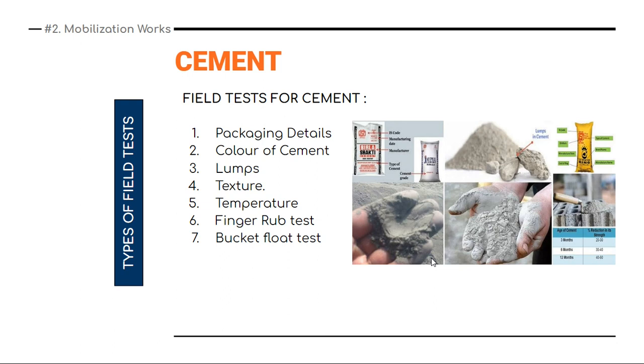It means that organic or inorganic materials are in there, so it is also not good. Then the temperature. When you thrust your hand inside a bag of cement, you should feel cool. If you don't feel it, then something is not okay, or there is heat continuously getting in and the cement is trying to set. Also the quality of the cement deteriorates accordingly. So you need to feel cool when you thrust your hand inside a cement bag.